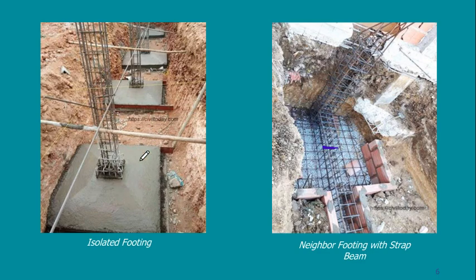And this was the shape of the isolated footings. But when I come to a column, suppose that this is the end of my property line at this location. In this case, all of this portion will be deleted from my footing, and the remaining will be this part only, and the column is not in the CG of my footing.